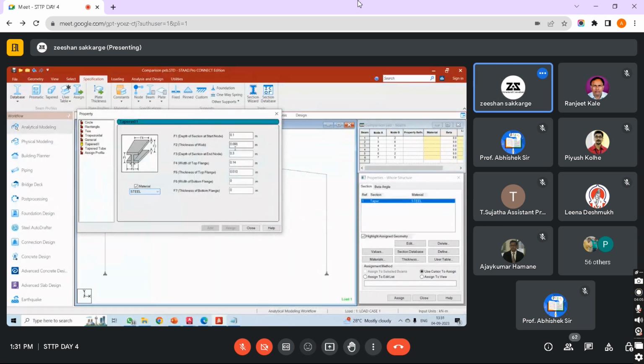So for the rafter at the end, towards the start, I want 100, and the width of my flange I will also take as 100, and 8 mm and 10 mm, that is fine. And this I will choose as 280; 300 is too much, 280 is sufficient.